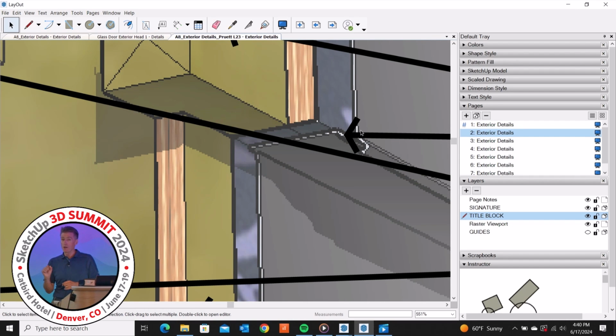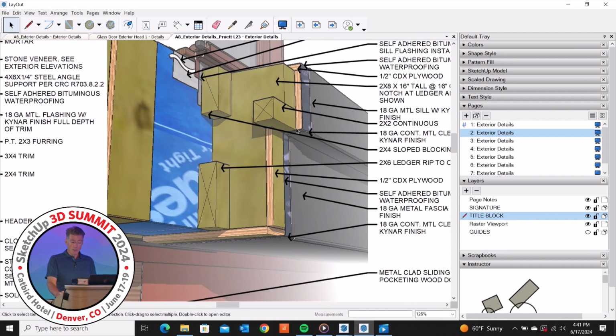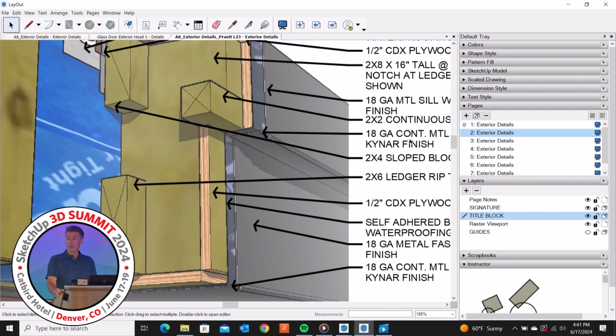On the underside, I wanted something more solid because I'm a big fan of using cleats to hold that top piece of flashing, because when it gets large, that really helps it be really stable for less chance of oil canning. I also spec some pretty heavy gauge. You can see a lot of these are done at 18 gauge, which is fairly thick and stable, but it gives a much cleaner look. In some cases, we go to 16 gauge for hot rolled steel especially. So we don't, the oil canning drives me nuts.